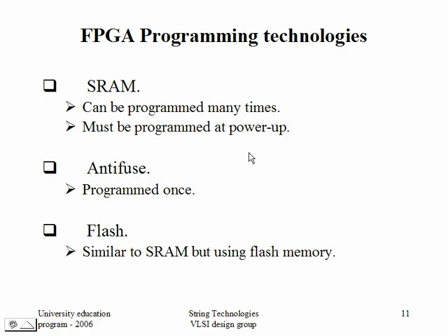You know the equation H is equal to I square RT by J. When I amount of current is flowing through some material with R amount of resistance, you can calculate that heat, and you can convert that into temperature. That is exactly the principle. When the current goes beyond a limit, the heat is such that the wire melts. So it is a wrong concept to put a bigger wire for a fuse and say that my fuse will never blow. If your fuse does not blow, your electrical equipment will go bad. So better to keep a fuse which blows at the appropriate current rating. Fuses are very critical. If you make a fuse which does not blow, your electric circuit will blow.